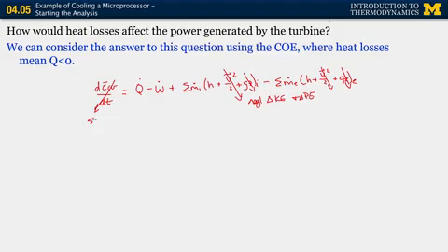We're going to assume it's a steady state device. And so what we did last time was we actually solved for this portion of the expression. We had the mass flow rate times the enthalpy difference. But now we have this heat transfer term that we're not going to cancel because we don't want to consider this adiabatic. Well, this is simply the adiabatic work that we just determined.